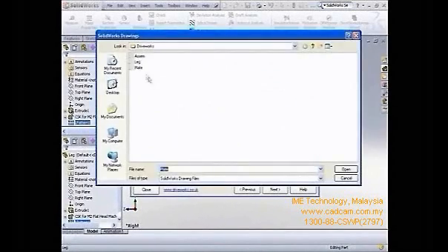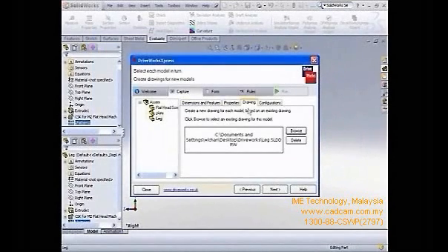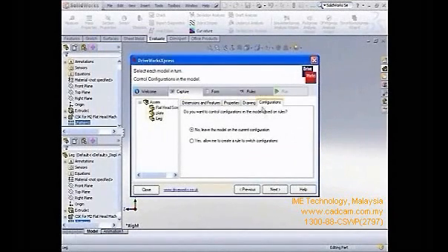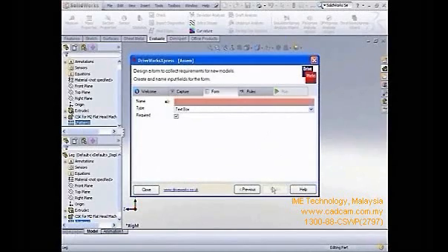After completing capturing the parameters, we move to design the user input form. Click on the Form tab. You are required to define the name of the field and the type of input data for that particular field. Start by keying in the project number and define the input type as text box. This means the data input in this field is treated as text by the program. Click Add and define another new field called Drawn By.